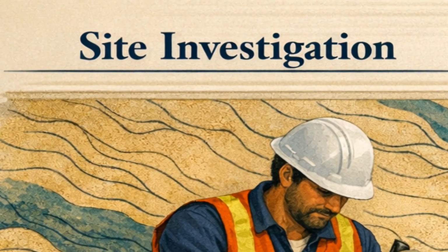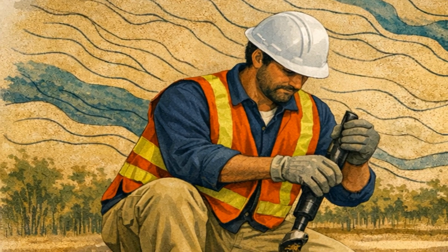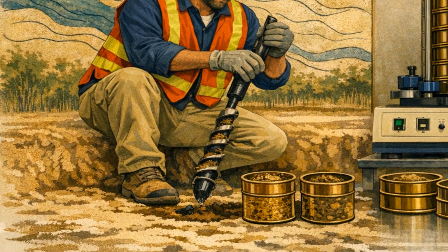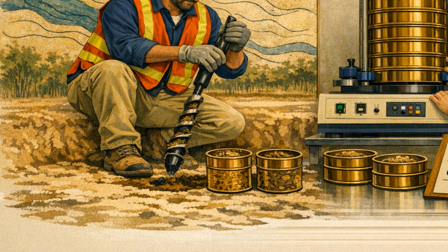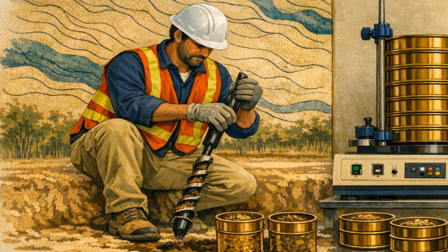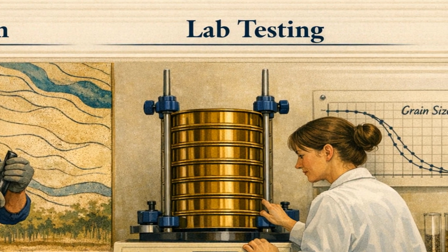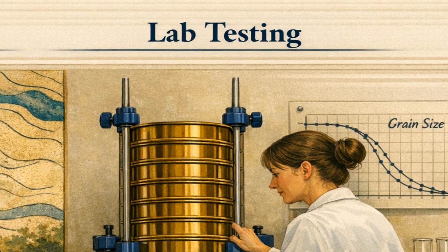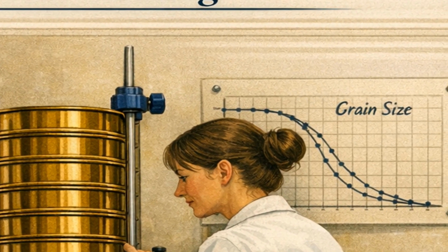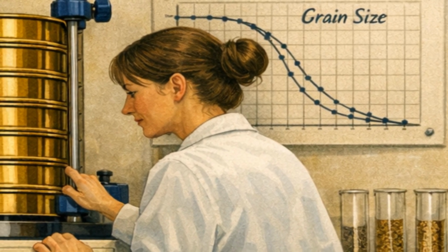The most crucial step in dealing with clay minerals is proper site investigation. Before any construction begins, engineers must identify the presence and type of clay minerals, especially the highly expansive ones like montmorillonite. This involves soil sampling, laboratory testing, and geological surveys. It's like a doctor diagnosing an illness before prescribing treatment. Identifying the specific illness, the clay, allows us to choose the most effective medicine, the mitigation strategy.